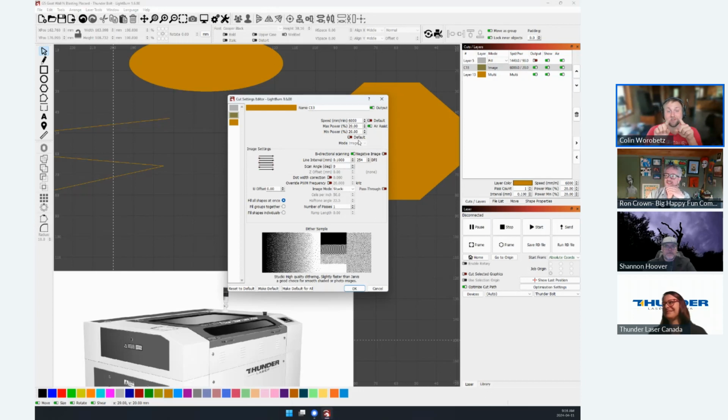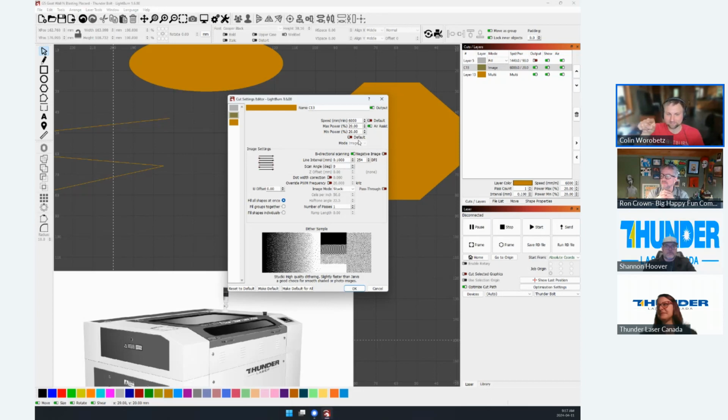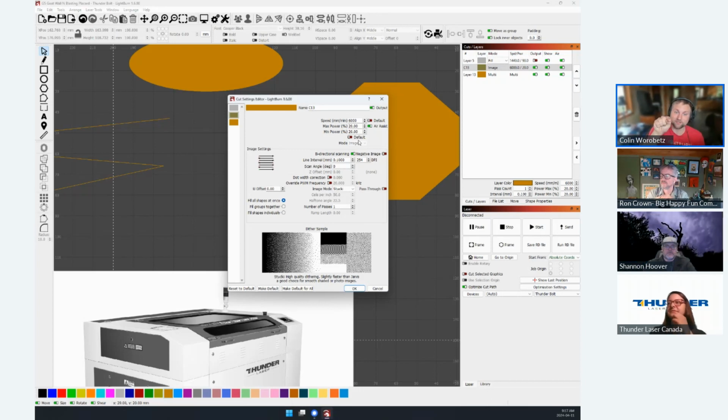This is fun. So say you're cutting a line. When your machine starts, it will be accelerating. It goes from 0 and comes up to say 100, let's just say, for speed. And the min and max dictates while it's accelerating, it starts at the min and then gets up to the max. So if you're coming into, say, a box, you start at 0 speed, and then you accelerate, and as you come in, you do that corner, your machine's going to slow down because it has to change direction. So the power will drop to that minimum amount, and then try to accelerate back up to speed, and then slow again, and run that box.